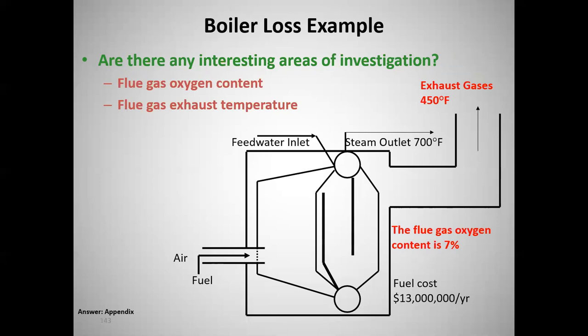Now, you start asking questions: you guys always run 7%? What's the boiler load? Well, the boiler load is 100,000 out of 120, so it's a pretty high boiler load. So they can't claim poor mixing. They're way too far up in the load chain for that. It may just be a cheap or not well tuned boiler or a cheap control system.